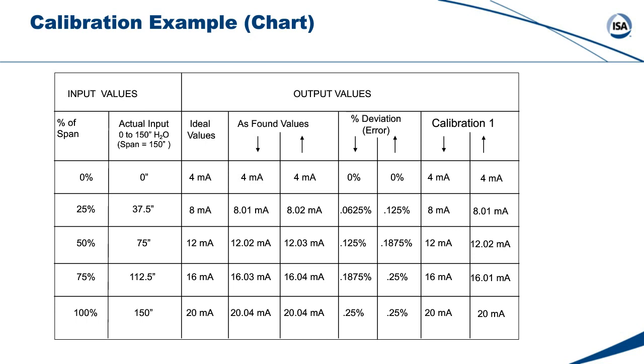One common mistake is that an attempt is made to calibrate an instrument already within an acceptable tolerance. The as-found values will allow us to determine if further calibration is required or whether we can save the effort and move to the next instrument.